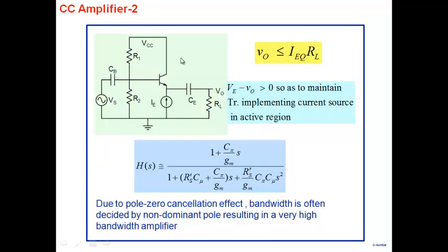And so that brings us to, again, the software always flips the current. I don't know why. So the current is down, okay? The current is down here. So a much better biasing, if you do want to use a common collector amplifier, is to use it with a current source. Because with the current source, you can use a much lower current to get a swing that you really want. From the other amplifier, you would require a much higher current here.